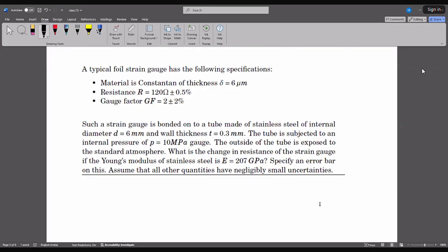Typically, the length of this strain gauge element, film or foil, increases and the cross-sectional area decreases, giving rise to some kind of strain. When there is a change in the cross-sectional area and the length, correspondingly there is a change in the resistance. That resistance change is reflected in terms of a net output.